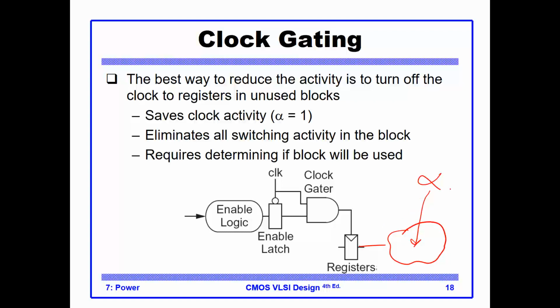Then I trace them back to a bunch of registers that are active all the time. Now, I notice that those registers are active when they are needed and when they are not needed. So, for instance, let's suppose these registers are feeding a floating point unit where it computes floating point math.